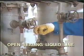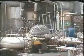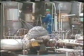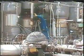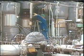Also, open the line which circulates sealing liquid to the stuffing box. Pumps which are used for pumping hot liquids must be warmed before the pump is started. This will prevent damage to the pump by unequal expansion of parts when the hot liquid enters the pump.